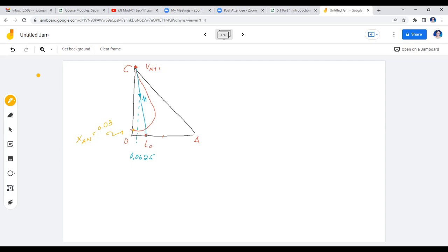Okay? Now, I think you would know what is expected now. So this is your L sub N, this one. That's your L sub N. So for you to be able to determine the extract, you just go up. Connect this L sub N in the lower part of the phase envelope with the M, and then extend until you rest here on the upper part of the phase envelope. And this is your V sub 1.